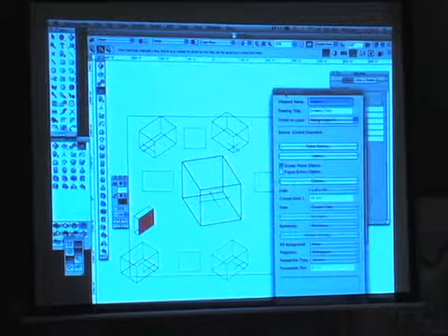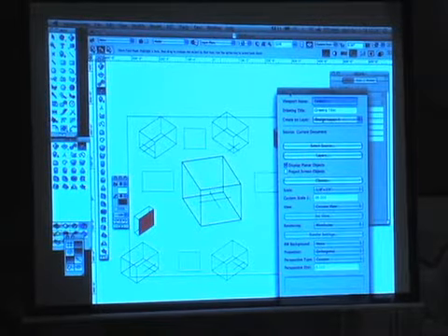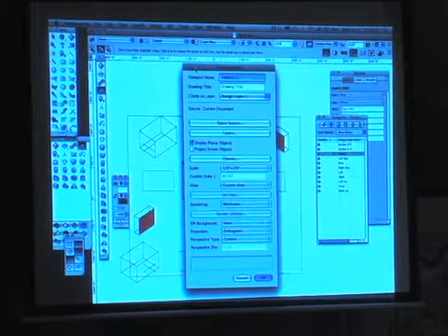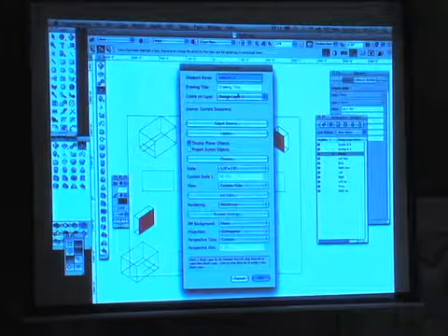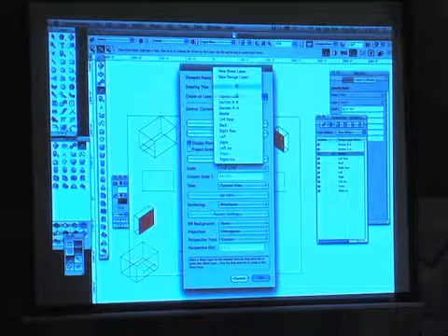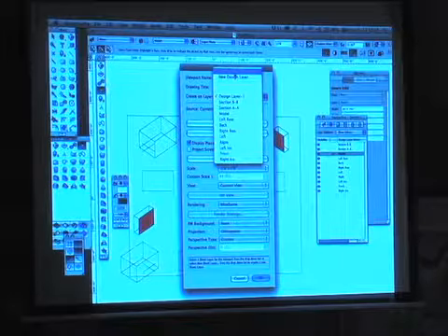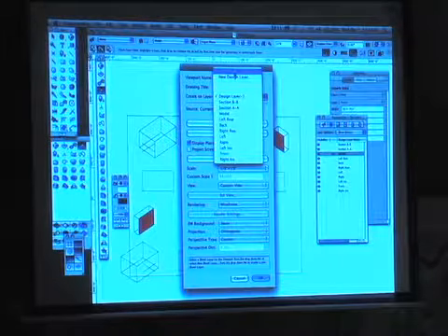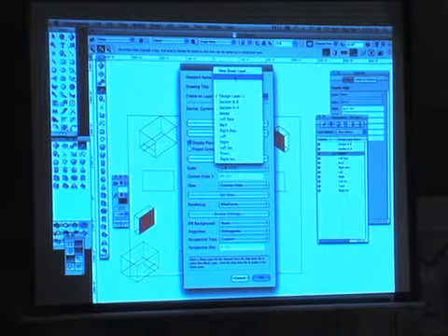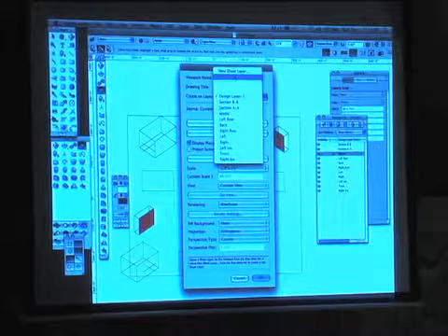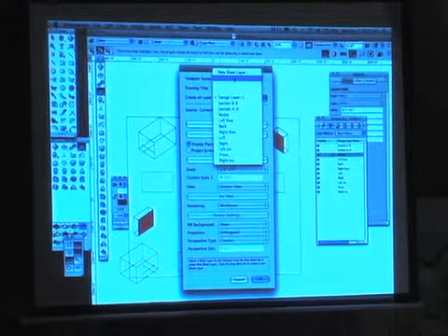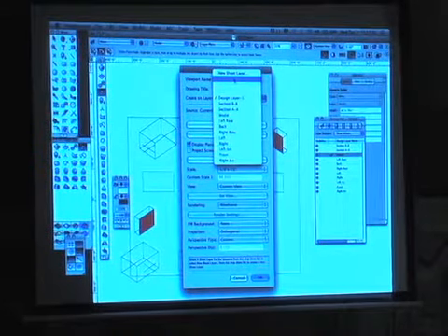So you have the viewports on design layers, you aren't working on a viewport sheet. No, we're working with putting viewports on design layers. Okay. Before, generally we'd put our viewports on a sheet layer and begin to set up our presentation page. Okay. And now you can put them on design layers. I think that came in 10, maybe 9, I'm not sure, where you can put them on a design layer. So that's what I'm doing. I'm creating a new viewport on a new design layer.